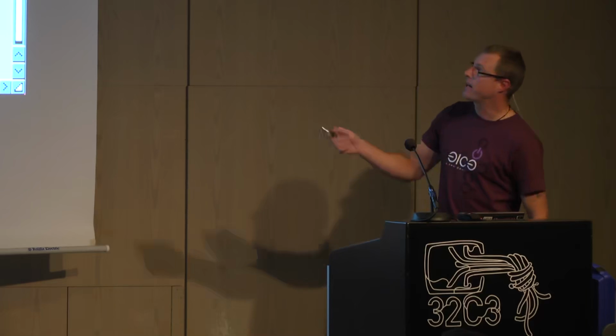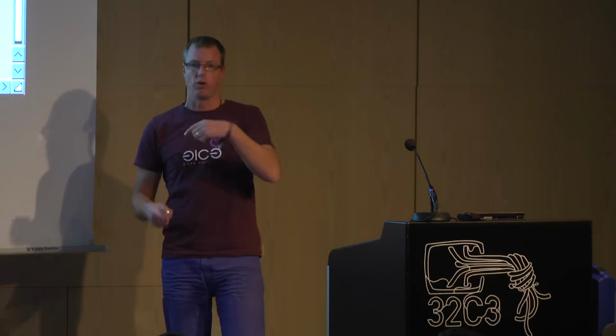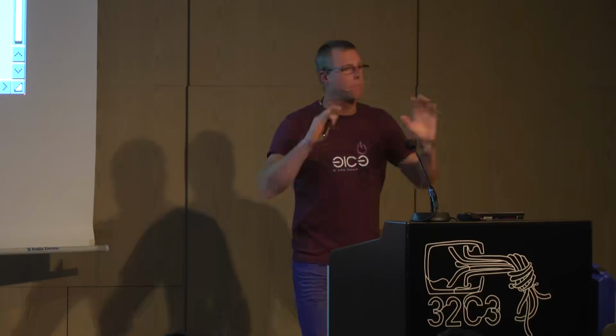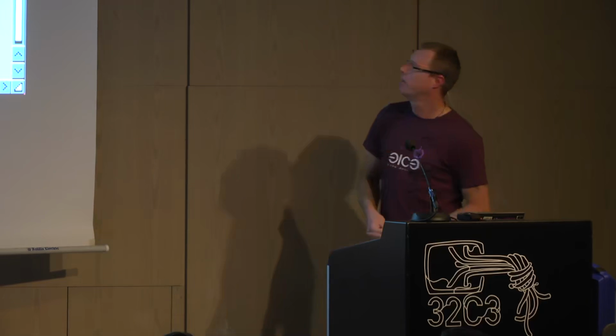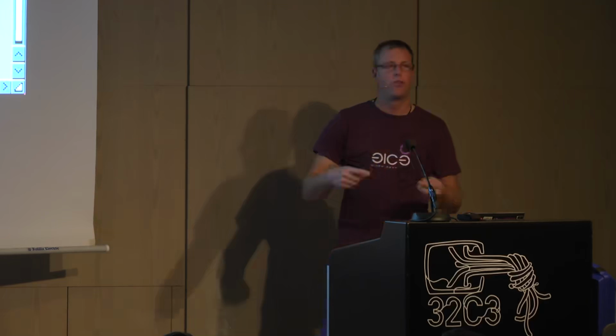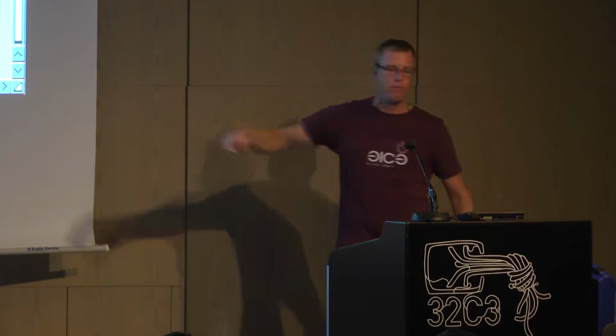It had 3 commands: the wait, the move, and the skip instruction. So you could wait for a specific beam position and then move, so write data to some register. At a specific position, you could modify, let's say, the sprite address, so you could start a new sprite at a specific position of the beam. And it had a skip instruction with which you could skip if the beam was already behind the location you were waiting for.